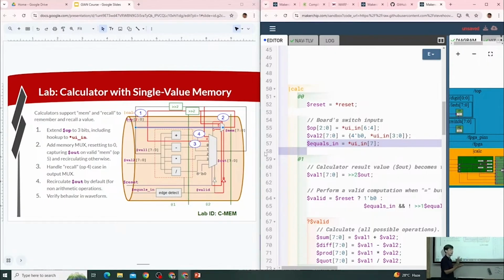But if we just imagine that we're in some unknown state and we just have 3 cycles of reset, right? We have those 3 reset transactions going through. We don't have the machine cleared out yet. It's in some random state deeper in the pipeline, but we march along and we're cleaning up in front of ourselves so the valid transaction can come along.